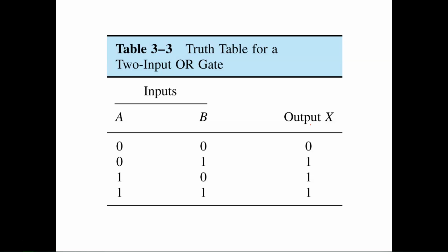Or if you have multiple positions inside a factory, or let's say you just have a big enclosure. So if I've got a big enclosure that I'm trying to work in, and I've got a start button here, a start button here, one here, and we'll say one here in the middle. That means that I don't have only one place I've got to go to start this. I can start it from any side that I happen to be on at that time, right? So it gives me the ability, no matter what position I'm in, to run the machine.